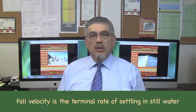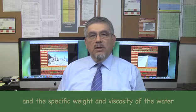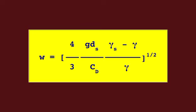The fall velocity of a sediment particle is its terminal rate of settling in still water. Fall velocity is a function of size, shape, and specific gravity of the particle, and the specific weight and viscosity of the water. For spherical particles, the fall velocity, derived from a balance of submerged weight and drag, can be expressed as follows. In which W is the fall velocity, g is the gravitational acceleration, D sub s is the particle diameter, C sub D is the dimensionless drag coefficient, gamma sub s is the specific weight of sediment particles, and gamma is the specific weight of water.